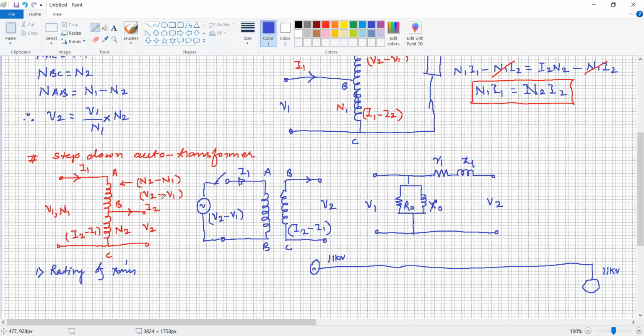To compensate that voltage drop, we may use this auto transformer as a booster transformer. This is one application. It is used in practical applications in the labs to change the voltage to conduct different practicals, as a variac, where a smooth change in the voltage is possible on the secondary side. This is one more application.